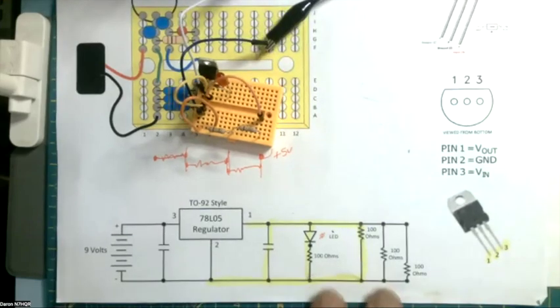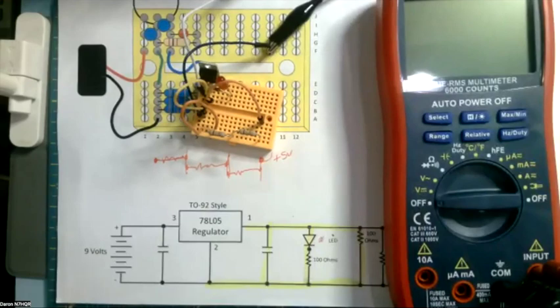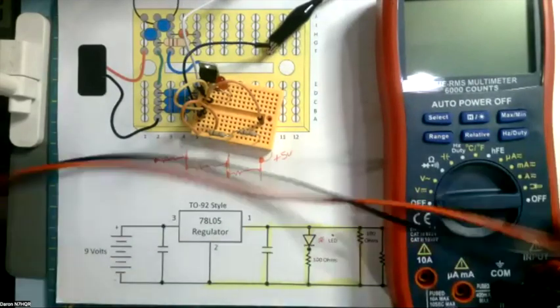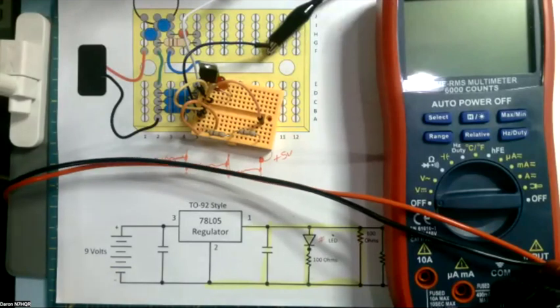You might say, I need a voltmeter, and somebody will hand you an old Simpson. If you're checking a battery, it won't make any difference, but if you're checking a voltage divider, like we're talking about, where you've got two 470K resistors in series, it will have a major effect on that voltage.